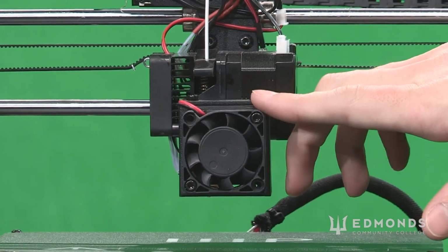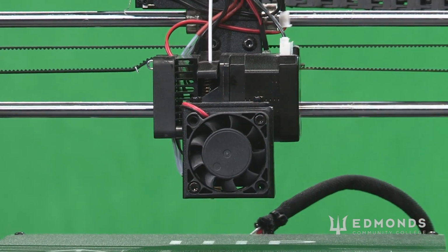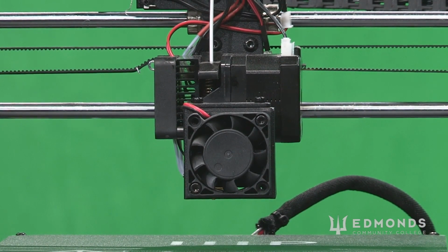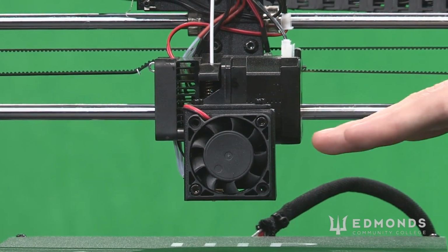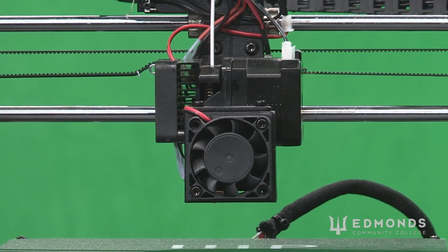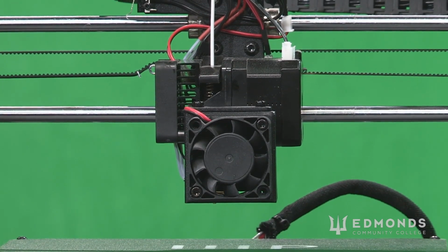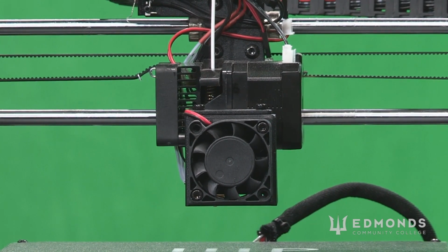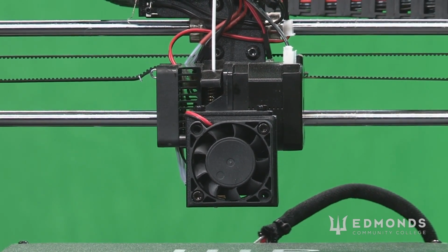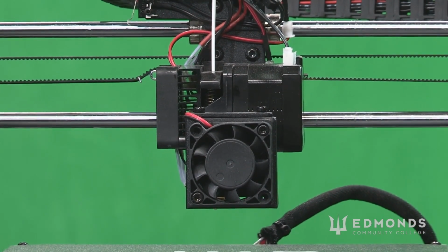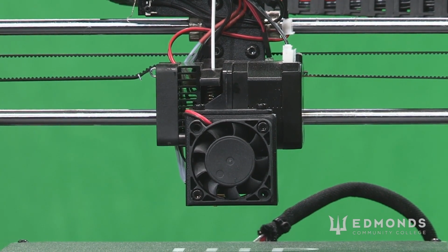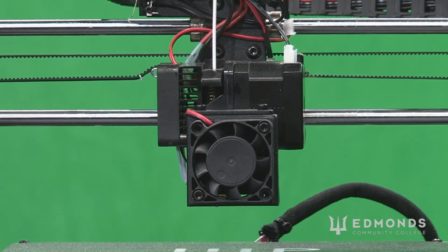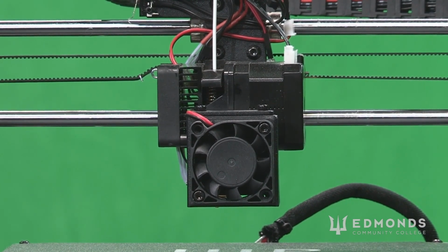We have here a fan which is not to be overlooked. It's not just for helping the extruder assembly get down to temperature afterwards, but rather, most importantly, this fan is cooling the plastic as it comes out. We're constantly making a balance between the high temperature that we want it to come out at in order for the plastic, in this case, to fuse to the previous layer, and the low temperature that we want it to reach quickly so that it freezes in place instead of changing the dimensions that we place it in.